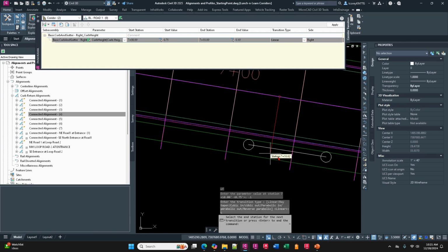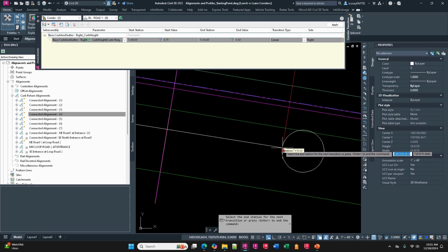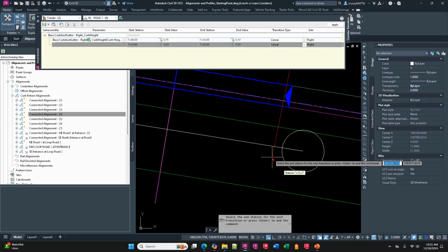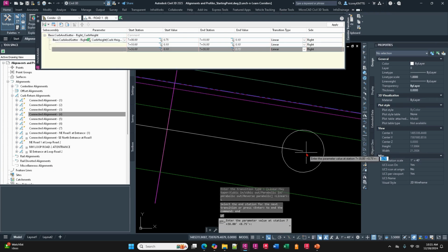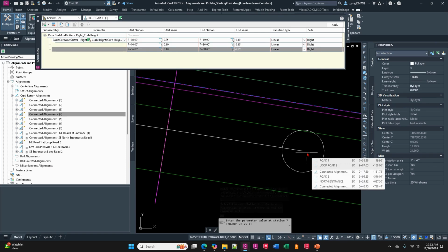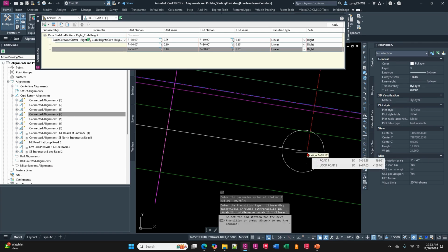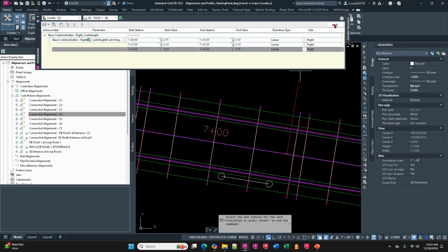And that's a linear transition. Then from there, now we're at 0.1. We want to go across the driveway to this intersection of line work. And we want to still be 0.1 high there and linear. Then we want to move up to this center of that circle, endpoint of that line. We want to go back to 0.75 at that point. That's linear. Okay, I think I have what I like. I'm going to go ahead and tell it to apply that.